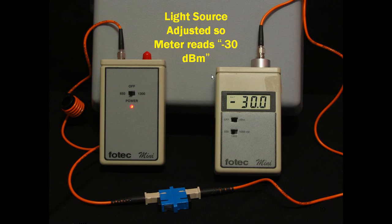And then over here on the right-hand side, we've got our power meter. Now this power meter reads in what's called dBm, or decibels reference to 1 milliwatt of light power. 1 milliwatt of light power is 0 dBm. Negative 3 dBm would be a half a milliwatt. And when we get down to negative 30 dBm, which you see illustrated here, that is 1,000th of a milliwatt of light power coming through from the light source to the meter. Now, let me just point out that this meter set you're seeing here is pretty old school. It's about 8 or 10 years old.